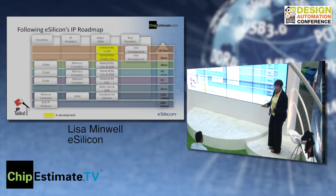And typically we come in when there's not something off the shelf that you would just be able to pick up and use. Let's say you need some aspect of a particular IP where you might want to harden it, you might want to control its footprint, you might want specialty IOs, etc. And on the tool provider side, we've done a lot of process development work where we have a tool that enables providers and IDMs who are developing their own processes to quickly build test chips and support their PDK development.